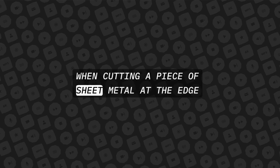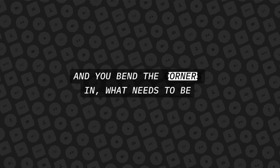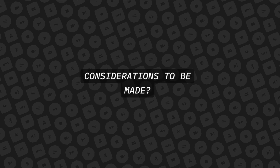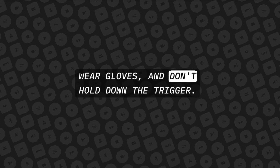When cutting a piece of sheet metal at the edge and you bend the corners in, what needs to be done? You must drill a relief hole. When riveting, what are some safety considerations to be made? Wear safety glasses, do not point the rivet gun, wear gloves, and don't hold down the trigger.